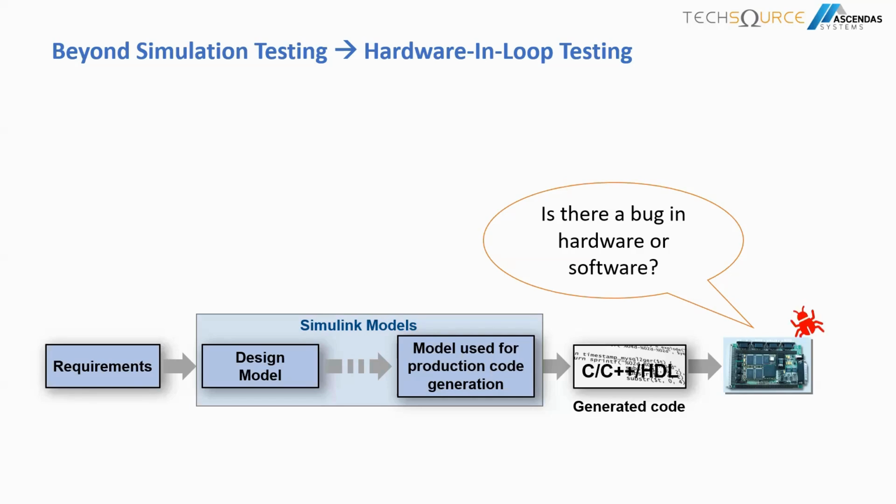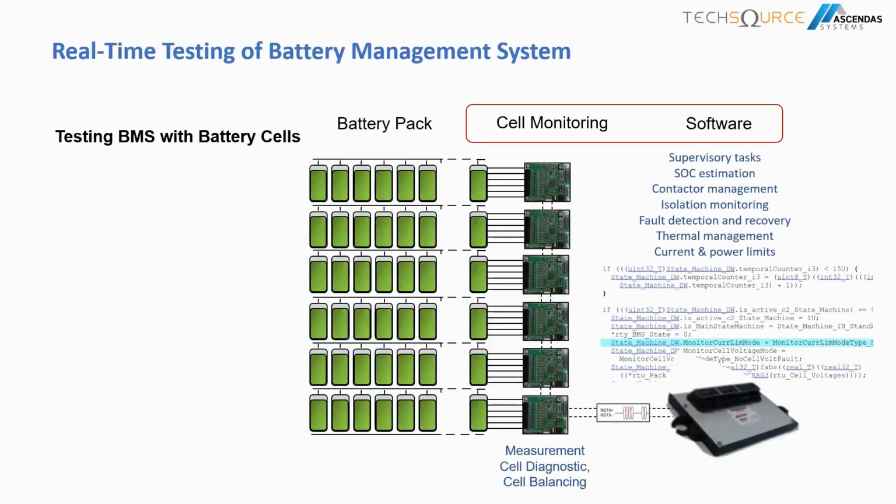If you have a real-time system where you run hardware in the loop, models run in real time and simulate cell voltages, pack current, and thermal behavior, and faults can be injected safely. This also automates our testing, reducing our testing time dramatically.